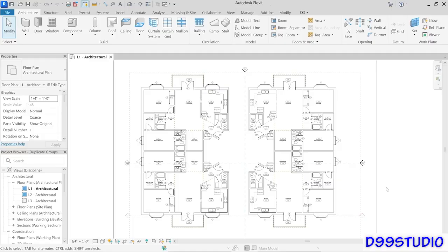So it's a little bit of a strange behavior there, but rather than panic, it was a pretty easy workaround to solve it. Now we've got the overall layout, and it was just a matter of doing a few quick duplicates with the mirror commands. Of course, there are some additional things that would happen here. You can box in some stairwells and some elevators and so forth. But you can see that if you're working with groups, you can very quickly create the majority of a floor plan layout just by copying and mirroring those groups around.